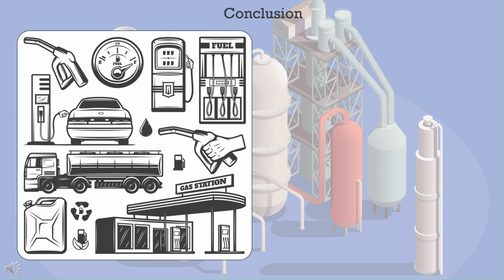Repairs and weld buffing address corrosion and mechanical wear. Proper torquing and sealing prevent leaks and structural weaknesses. The entire process minimizes unplanned downtime and extends the column's service life. This structured maintenance approach ensures that fractionating columns operate safely and efficiently after shutdowns, supporting continuous refinery operations.